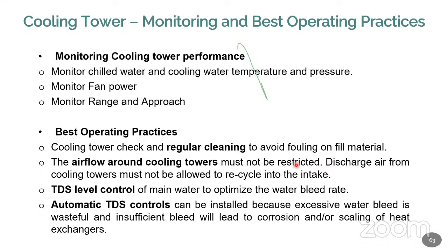So what are the best operating practices? For the cooling tower, you have to check for regular cleaning, because whenever the water passes through the fills, because of the quality of the water, automatically the fouling effect will be there. So that should be properly cleaned so that your heat transfer takes place.